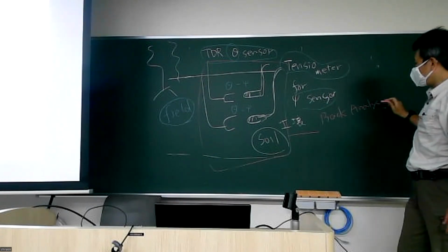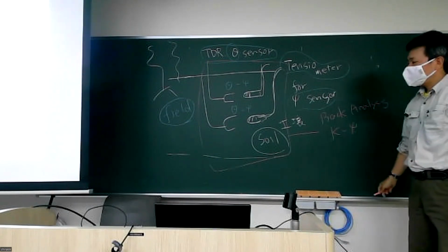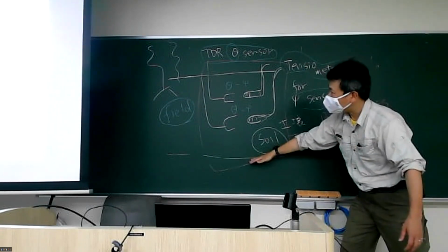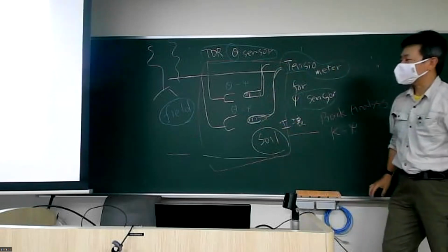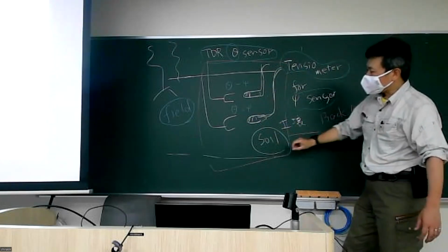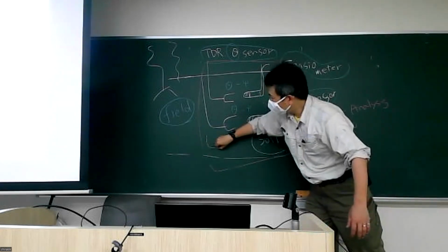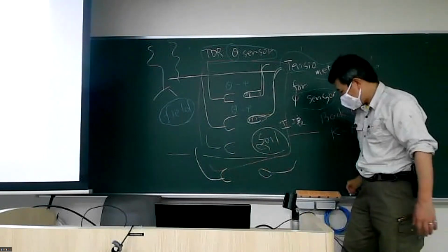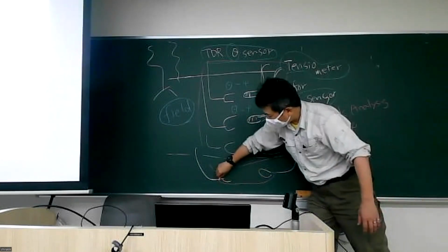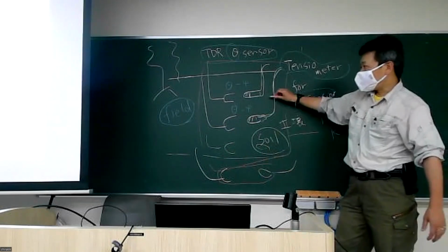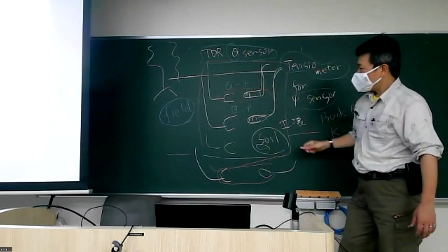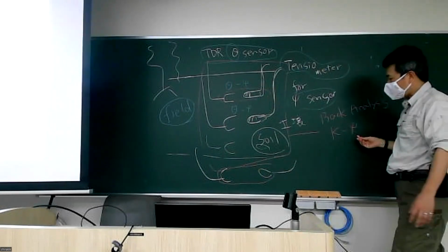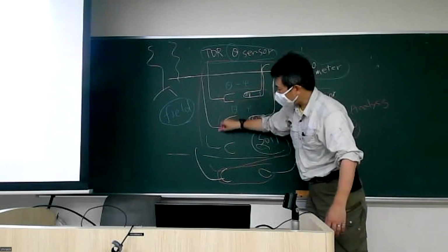We can consider this as a one-dimensional cross-section, and for example give the lowest data and the top data as given, and then derive k psi here. For example, we make some layers with TDR and tensiometer. We use the lowest value and the top data as given. Then we can do back analysis by checking the parameter change, then k psi for this area.